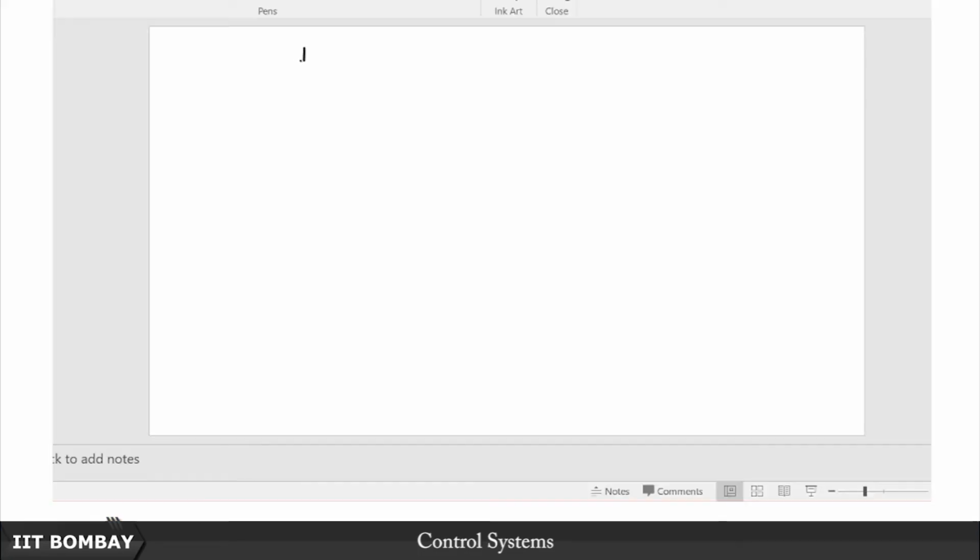Of course you can artificially create redundancy if you so desire. For example, if someone wants to write 1 upon s plus a as half upon s plus a plus half upon s plus a, and then realize it as two integrators in a parallel realization, then of course we can't help it. But these are defective cases where you are deliberately introducing this sort of redundancy to prove me wrong, in the sense that, look, I started with a transfer function that has no pole and zero in common, and yet I came up with a realization which is really not minimal.